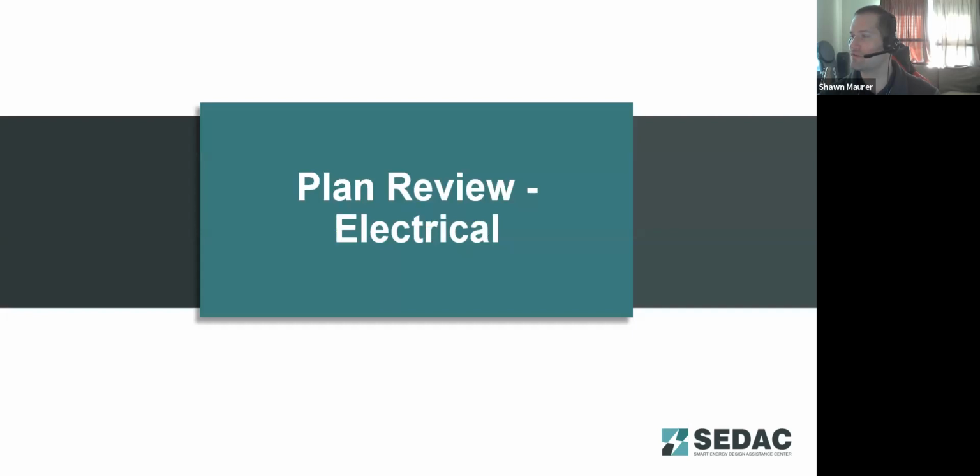We do have another poll here covering those mechanical sections, so I wanted to launch that polling. Which of the following needs to be documented in the mechanical plans? It is a multiple selection answer, so select everything you think is correct. Do you need to document the duct pressure class, duct sealing locations, mechanical equipment capacities, and a control narrative? And then for the energy code, does that require hot water circulation systems for domestic hot water systems, true or false?